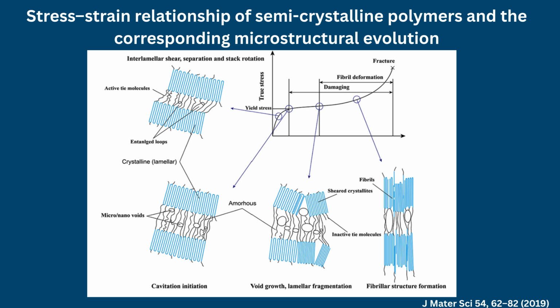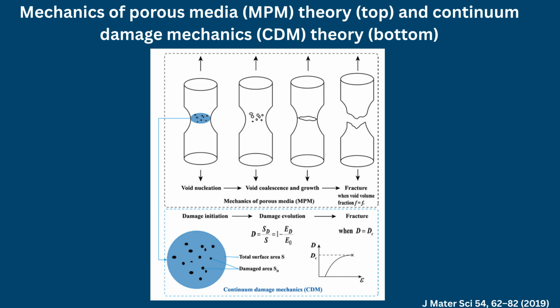Conversely, appropriate molecular weight distribution, branching, crystallization history, and lamellar morphology can produce highly ductile behavior, despite substantial crystallinity. The brittle to ductile transition therefore reflects a competition between plastic yielding and fracture rather than Tg or crystallinity alone.